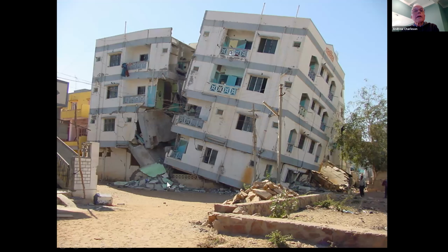Here's another building where the ground floor has disappeared because of a soft story. Originally before the earthquake, there'd just be columns underneath this building. But you can see that above, the columns are infilled with partition walls that make it very stiff and strong. And so the soft story was just so weak that it collapsed.